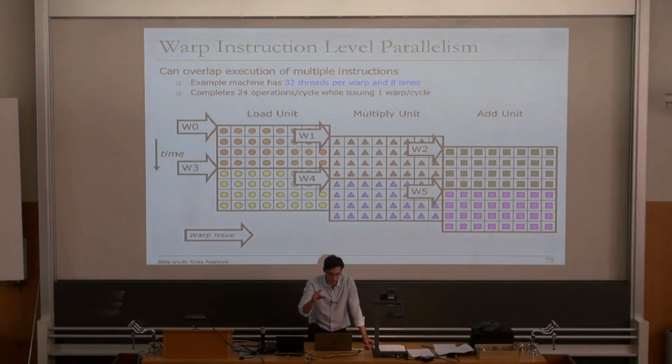The next generation, launched in 2010, has 16 vector lanes for every 32 threads. The one launched in 2012 has 32 lanes. Interestingly, in the last generation, if I'm not mistaken, they have returned to 16 lanes. So I guess it depends on engineering decisions. There is no specific reason from the theoretical point of view that we are analyzing here.